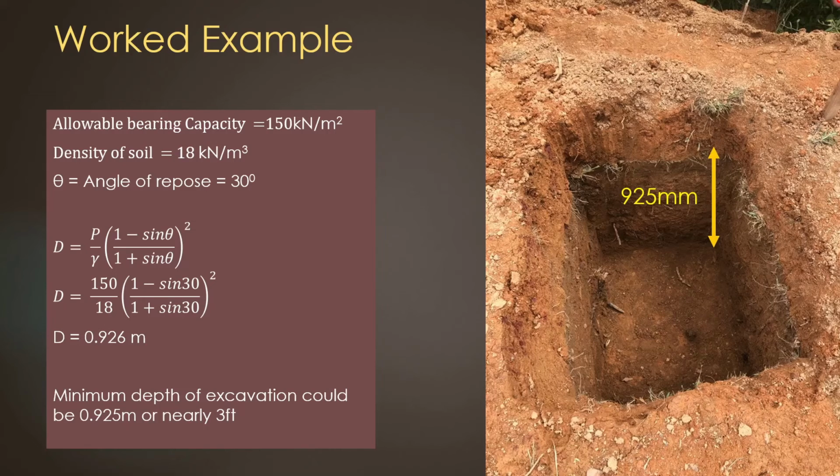This applied pressure could go up to 3 story or 4 story buildings. Depending on the grid, you may decide the pressure, because column load is the factor that determines the pressure. So you have the foundation footing and you know the area of the footing.